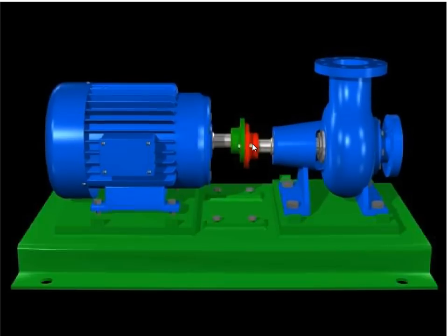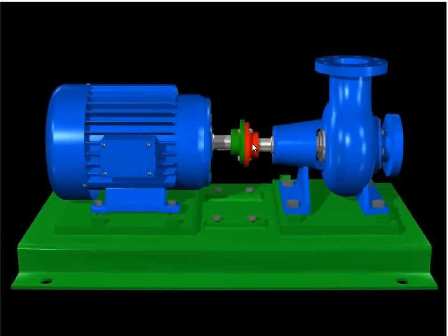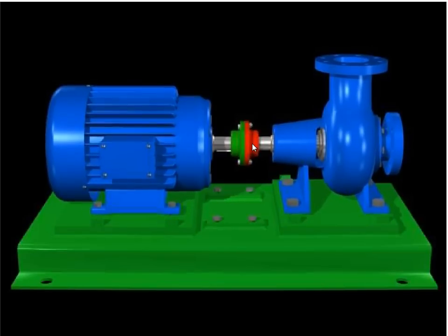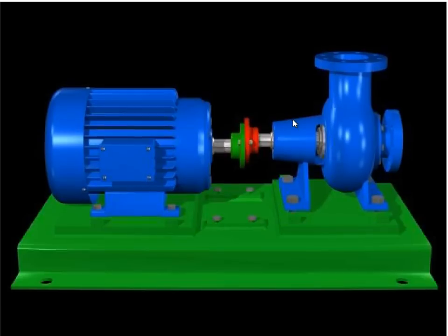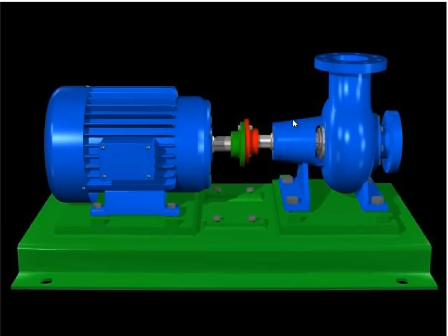Now, I'm simulating it. We've got the bolts undone, and it's free to move up and down. Maybe we're out in space. But of course, we're going to bolt the machine down, but the forces are still there. So if I put a sensor here and a sensor there, they are 180 degrees out of phase, whether I measure them both vertically or measure them both horizontally.